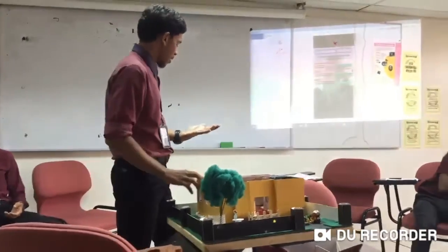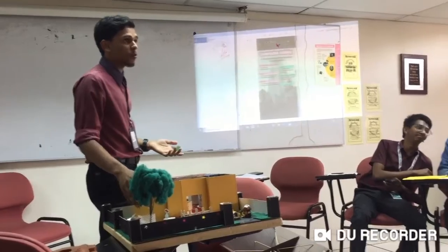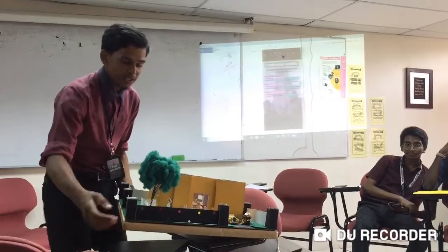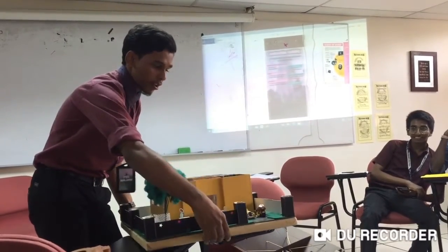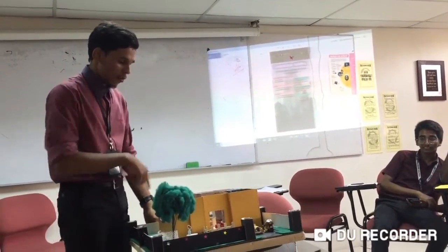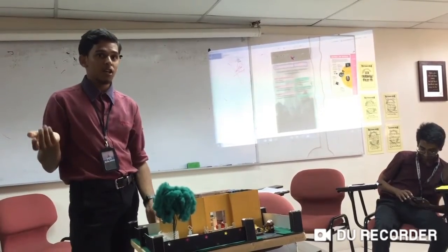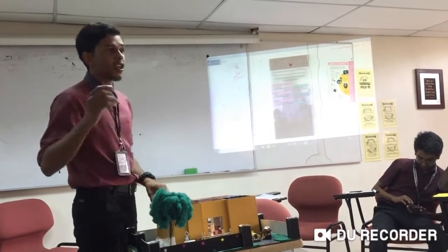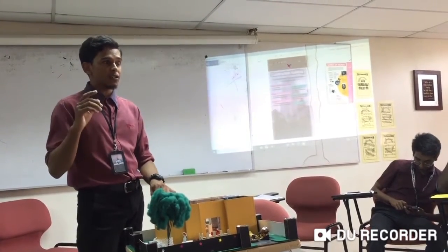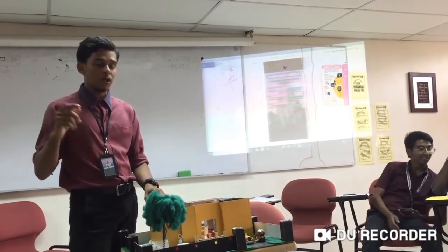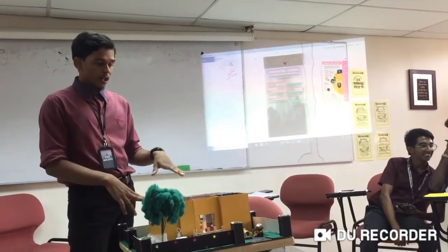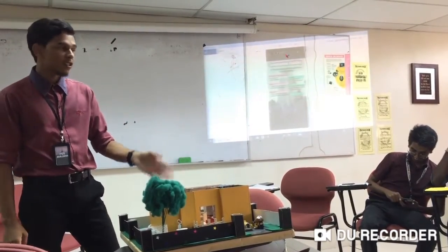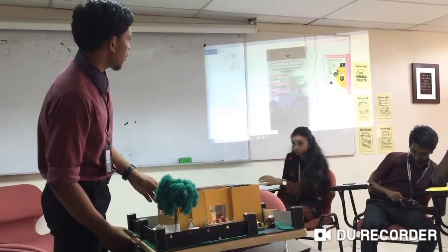And then there are three phases of IBS. The first phase is marking the lines on the foundation. First, they make a foundation here. This is an example. This is the foundation. They mark lines on the foundation as a reference to fix their panels, and then the installation of the mold. We can also call it a panel mold. They design the mold at the factory and then bring it here and fix it.